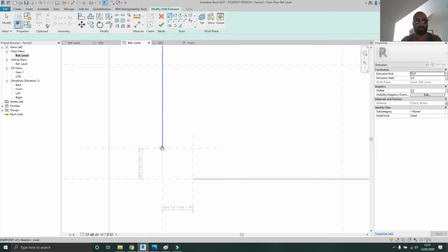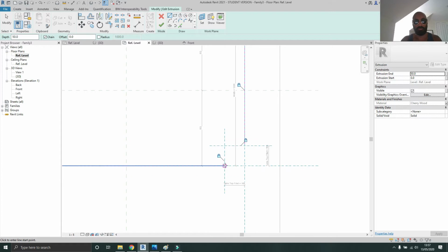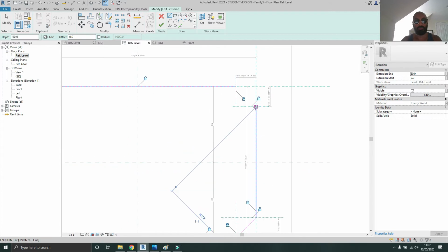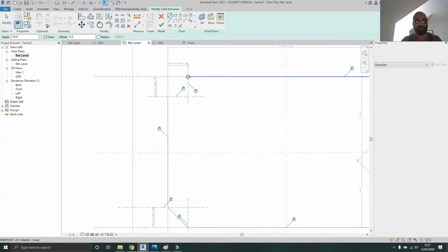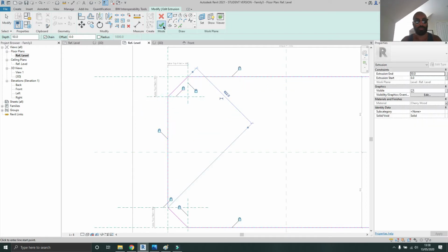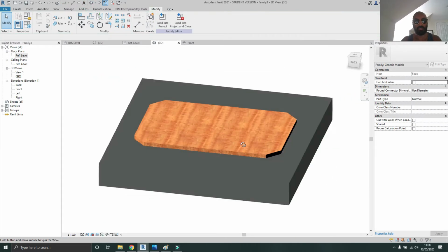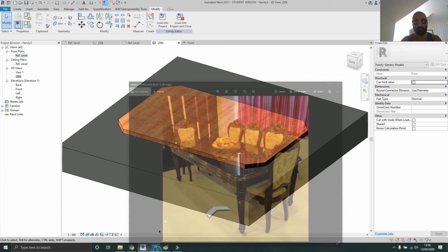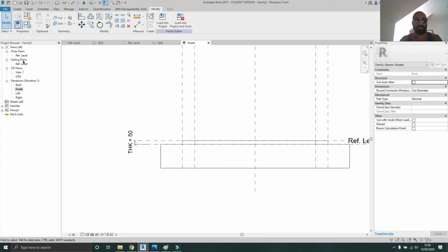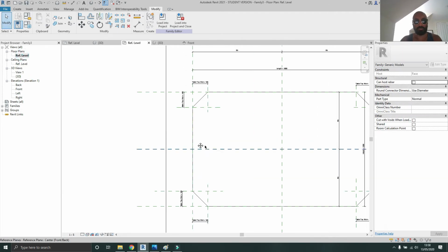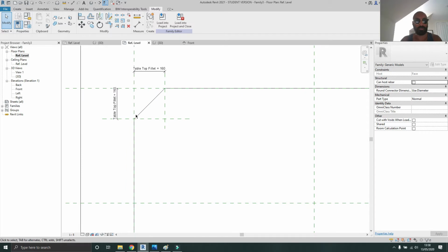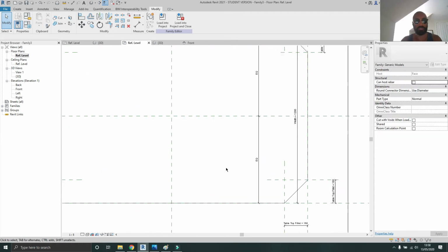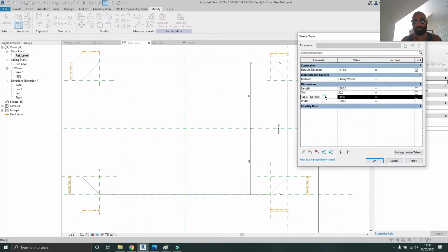So now that those points are locked, when we connect them, these points will be automatically locked to those points because it's an extrusion. And there you go. That's the fillet done. These parts here, and remember I've done them as 45 degrees. Well, mathematically, I shouldn't really have to explain this, but because this side and that side are equal, this angle here is automatically 45 degrees, and I can change that from the tabletop fillet thing here.